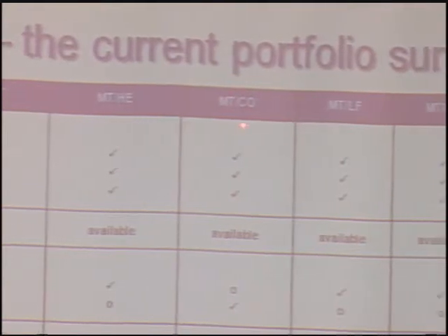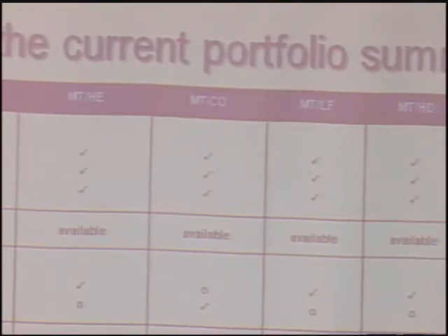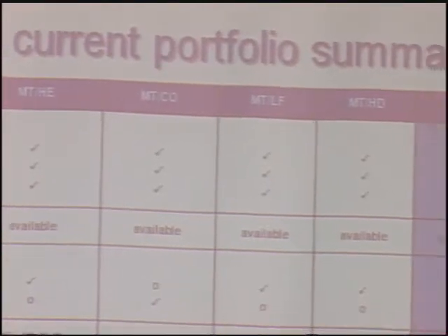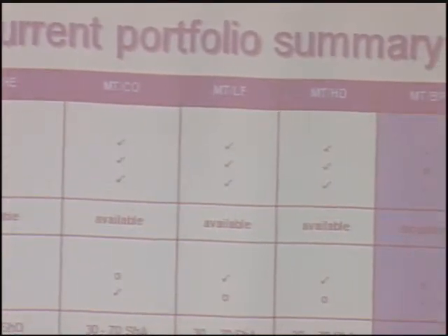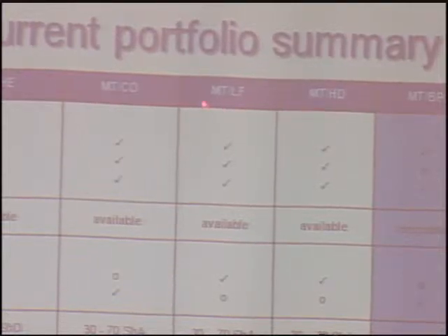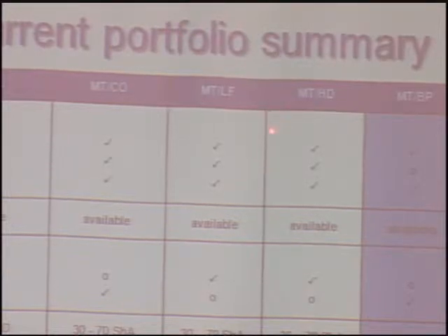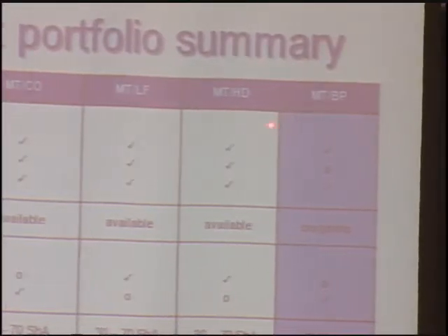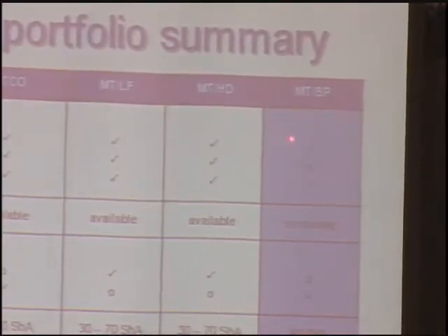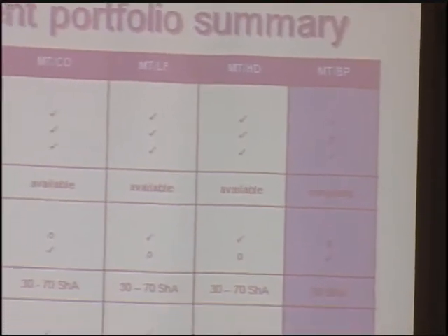This series is intended for co-injection molding for overmolding application, with adhesion to PC, ABS type of engineering plastics. We also have low friction materials and high density materials. We are developing barrier property TPEs.